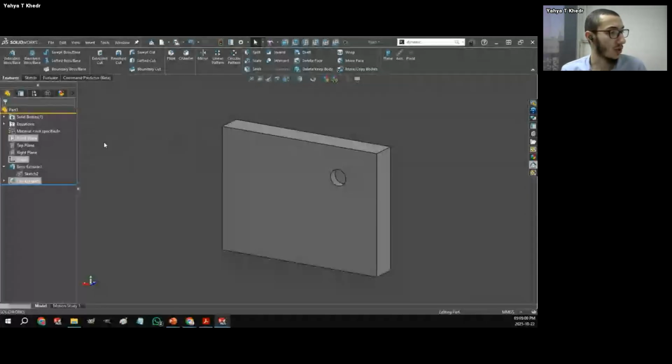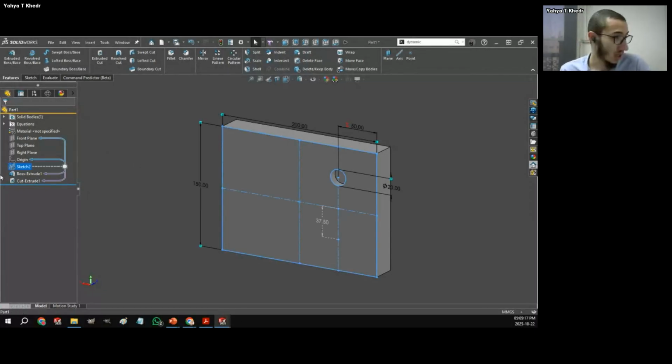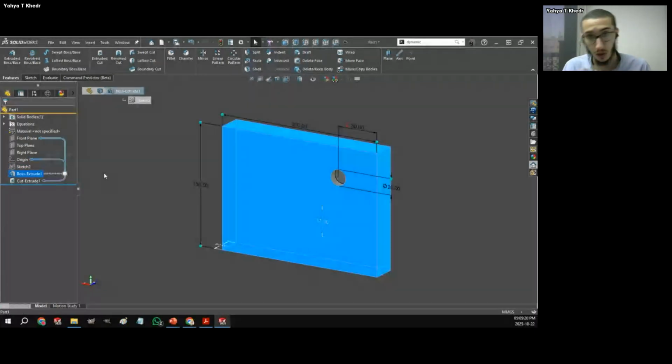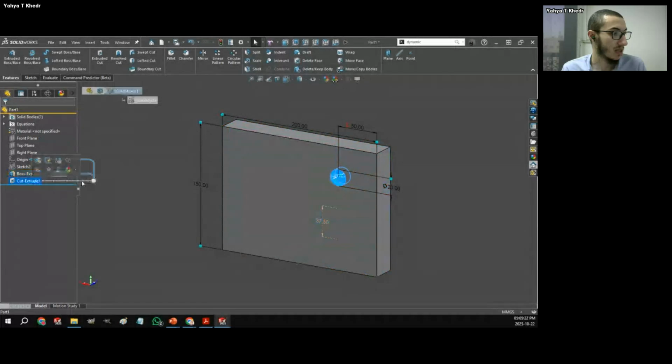And if I would go into a flat tree view, if I click Control T to go to this flat tree view, instead of having the boss extrusion and the cut extrusion linking the sketch underneath them, in this preview it's even easier to say, okay, this sketch is now identifying those and those. If I click on this one, it's now identifying those and those, and so on. You can very easily go ahead and see what defines the position or the orientation or the value or the shape of the different other features as well.